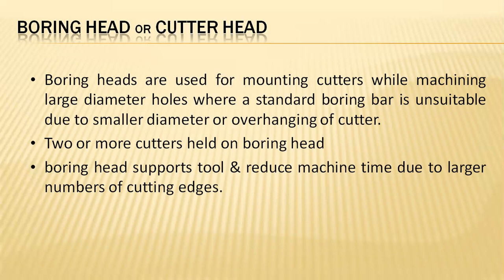Normally, these boring heads are used for mounting cutters in the machining of large diameter holes, where even a standard boring bar is unsuitable due to the smaller diameter. Even two or more cutters can be held on a boring head, which supports and reduces the machine time because of the large number of cutting edges in this machining process.